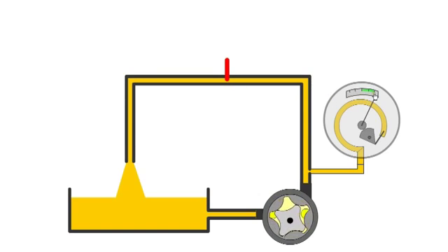We cannot close the valve fully because this is a positive displacement pump. If the valve is fully closed, pressure will rise sharply and something will break. Usually a pressure relief valve is used to protect against this situation. When the valve is opened, there is no restriction and we lose oil pressure.